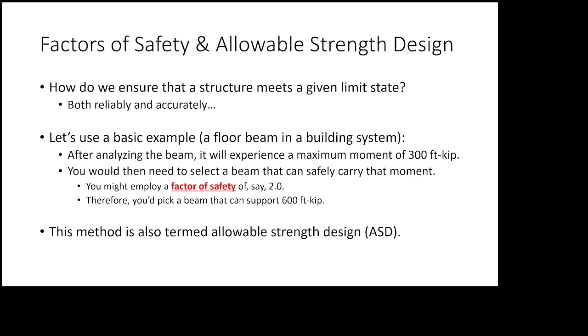Now, what type of engineering system do you think gets loaded, unloaded, loaded, unloaded, loaded, unloaded throughout its design life? Bridges, there you go. And so in bridge engineering, we have to assess conditions related to cyclic loading. And there are oodles of discussions we could have about that. What is the difference between low cycle fatigue and high cycle fatigue?